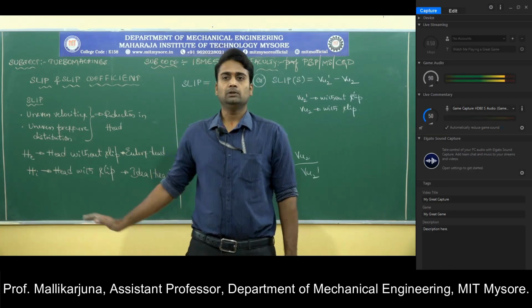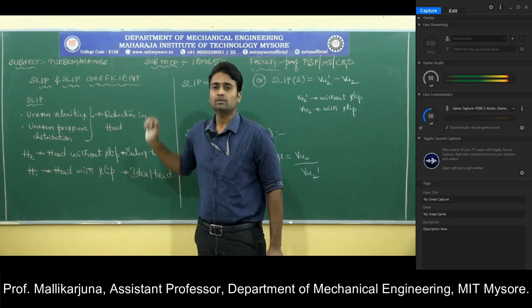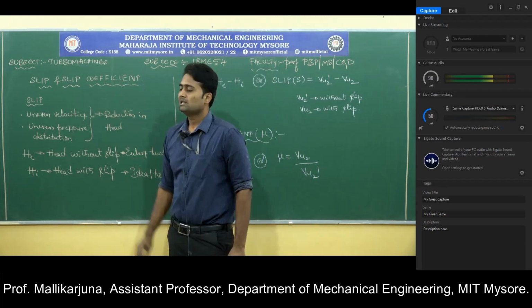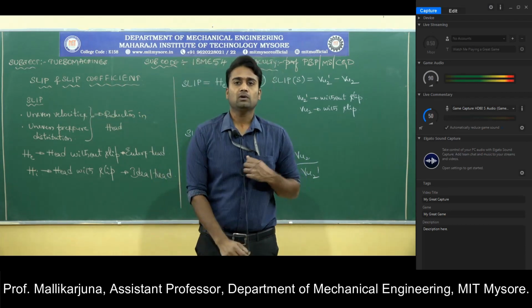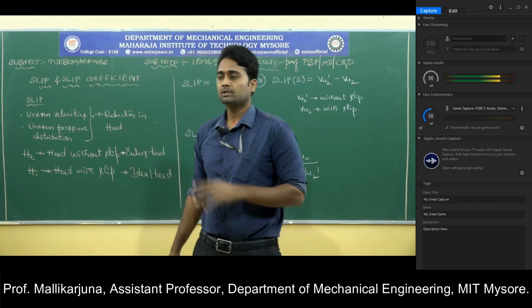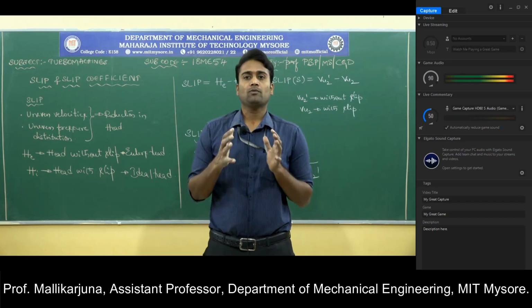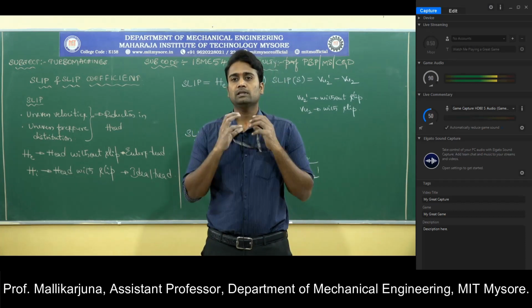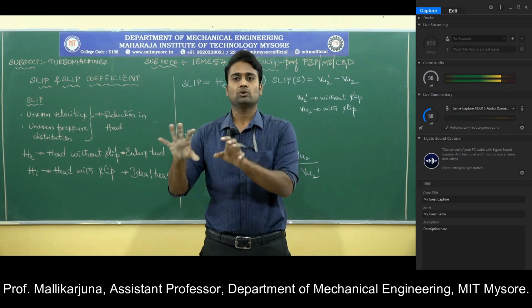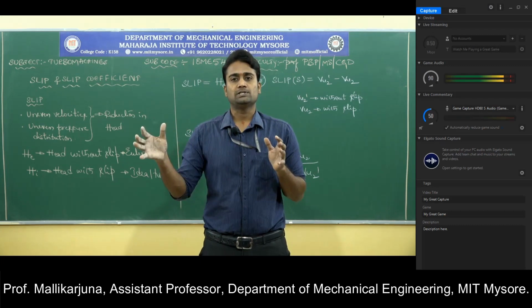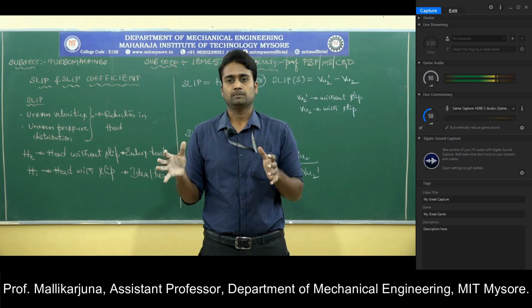Okay, let us look at a few of the terms with respect to the centrifugal compressor. The very first one is slip, the next one is slip coefficient. In order to understand slip and slip coefficient, we need to have a certain theory with us. What we have understood till now is that in a proper passage, wherein there is no disturbance, the velocities are not disturbed.